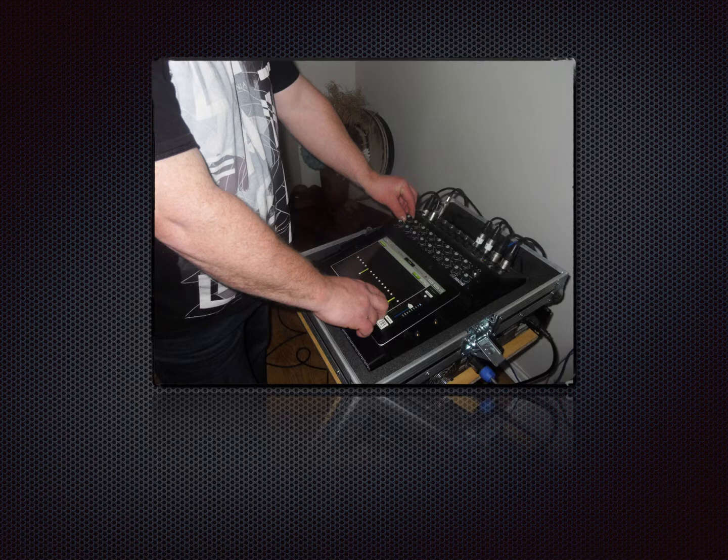Before we can use the PA, we need to set the system up as we intend to use it in order to ring out the PA. We now need to set the input gains on each channel. By singing into the microphone, we can use the gain control to set the maximum input level without the level clipping. This is repeated on all channels used.